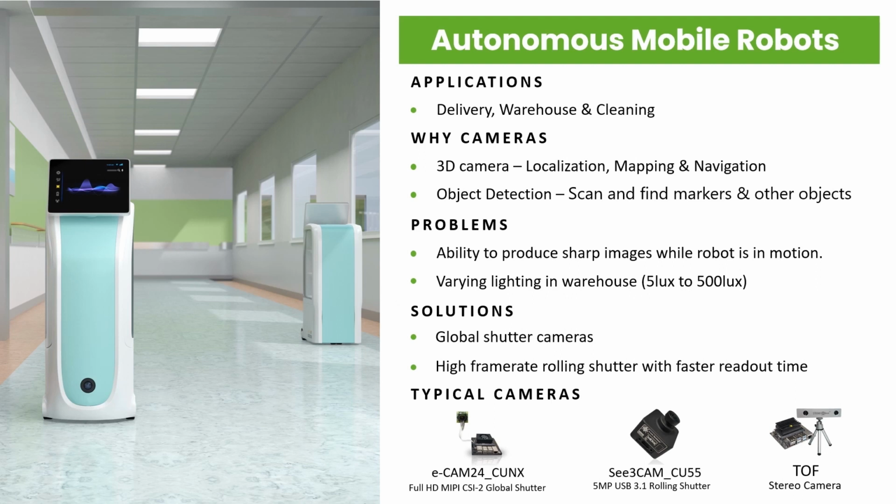If you are thinking about a camera for performing obstacle avoidance, select a 3D camera which is based on stereo vision or time of flight technology. Stereo vision cameras use two monochrome global shutter cameras in sync with each other, while TOF cameras use an IR based laser light source. They both can produce good results while used in a close range and under a controlled lighting environment.